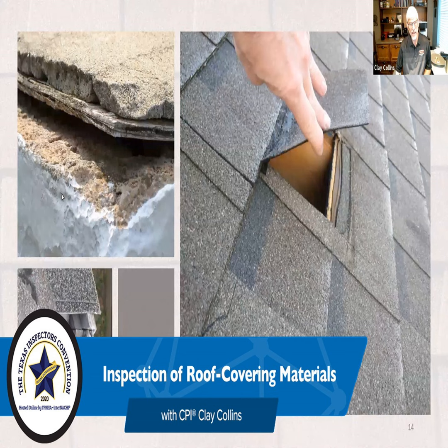Down in 1 and 12, including those shed roofs that get installed over a patio, if it's attached, sometimes the homeowner will just go straight down onto that. I've seen it done without any flashing. So you go from a steep pitch or a normal pitch down to a low pitch with no flashing. That transition is why you end up with roof leaks on those patio covers.